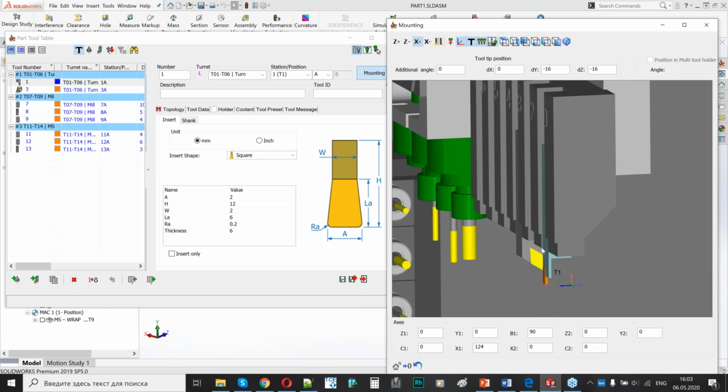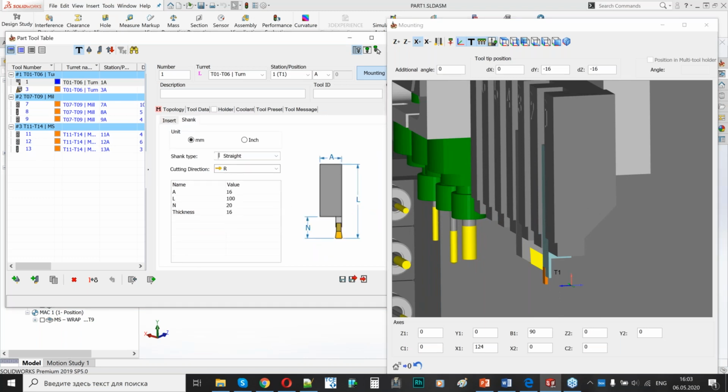As you remember, I added a right-handed tool and then I flipped it because I wanted to show how the tool position can affect the machining length parameter, but I didn't mention that in real life, programmers try to avoid flipping a right-hand tool on Swiss type machines. This position can be used, but for a left-handed tool. Why? Because of rotation direction.